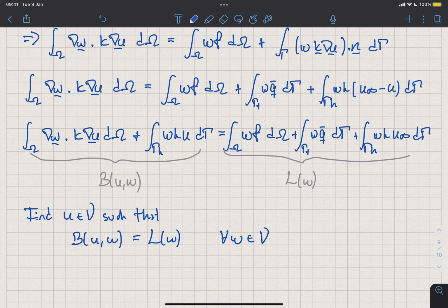Okay. Remember that if you have a zero Dirichlet boundary condition, and that's all you have, then you are basically dealing with a trivial solution where the temperature field is zero everywhere. Now, you're talking about the case where you have non-zero temperature. And in that case, remember that whatever prescribed value of the temperature field you know is going to end up in the right-hand side, modifying your force vector. Yeah. That's what you mean. Yeah. But I like the part where it drops out, I didn't really understand that part. Maybe it's just me.